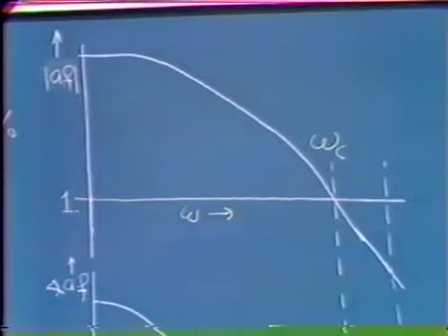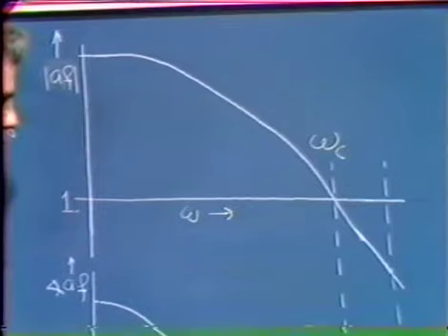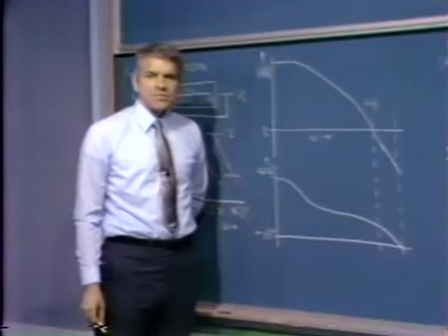I'd also then like to define the phase margin of the system. And to determine the phase margin, assuming we have a stable system, incidentally, for any of this, we really have to go back and check via a Nyquist test whether the system is stable or not. But we've very rapidly learned to recognize familiar patterns.